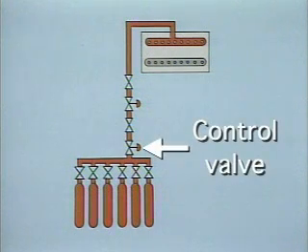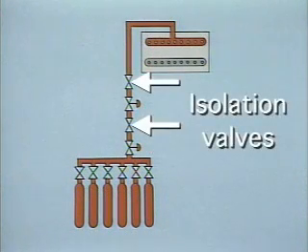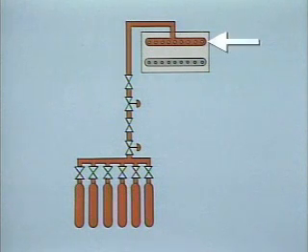First, a pressure control valve is used to maintain the supply pressure from the cylinders at about 100 to 125 psig. For safety, isolation valves are used in addition to the control valves to shut off the flow of hydrogen completely. A second automatic pressure control valve maintains the pressure at which hydrogen is supplied to the generator at a lower value, 30 psig in this case. The piping carries the hydrogen to a manifold inside the generator. From there, it is dispersed within the generator casing.